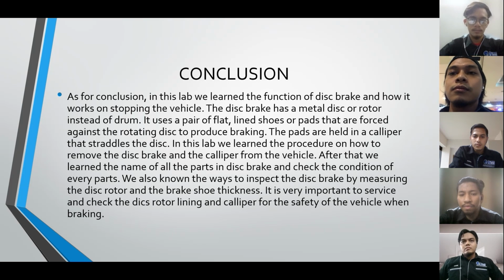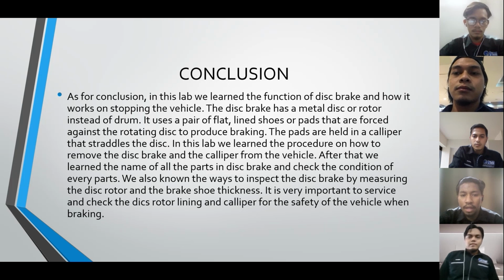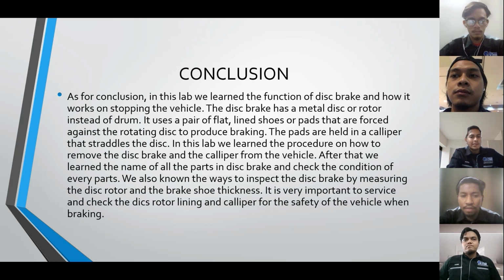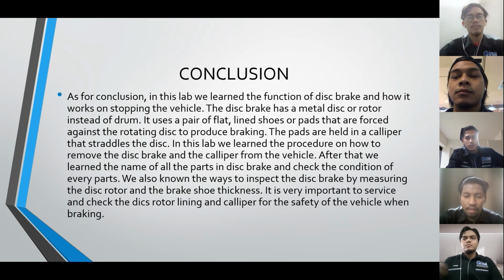In this lab, we've learned the procedure on how to remove the disc brake and the caliper from the vehicle. After that, we've learned the names of all the parts in the disc brake and checked the condition of every part. We also know the way to inspect the disc brake by measuring the disc rotor and the brake shoe thickness. It is very important to service and check all the disc rotor, lining and caliper for the safety of the vehicle when braking.